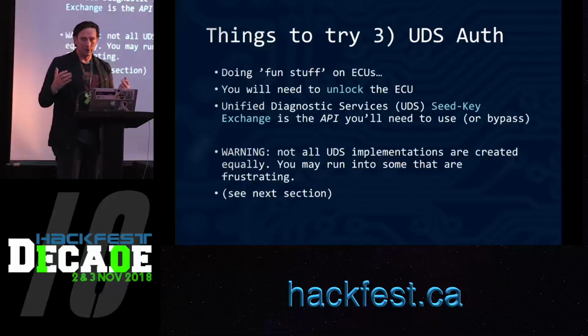All right. So remember, OpenXC is taking JSON definitions of what a signal is, like tire pressure, and encoding that into some kind of a binary structure that's in those flat binary files. And what we want to do is reverse this arrow, because if we can reverse that arrow, then we can drive our own custom cluster, or maybe make one of those cool oil temperature gauges or turbo gauges that you pay an extra 20 grand for an ST or something like that. Just make your own, right?